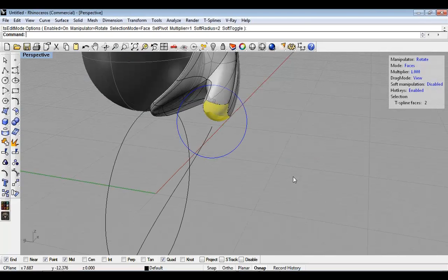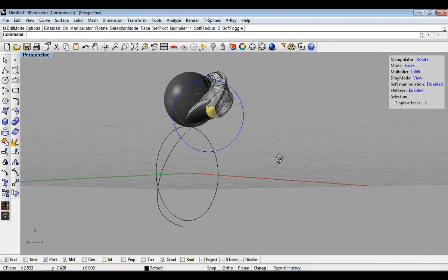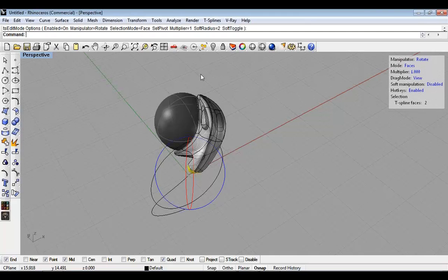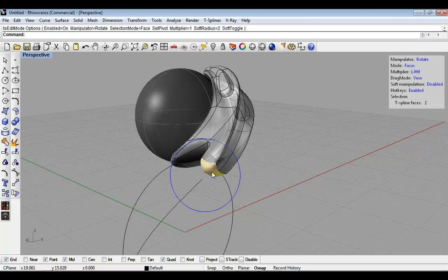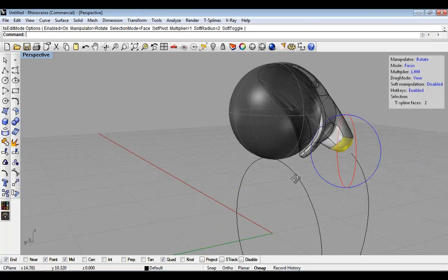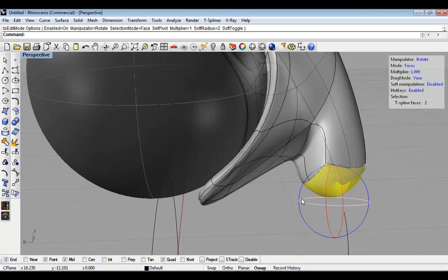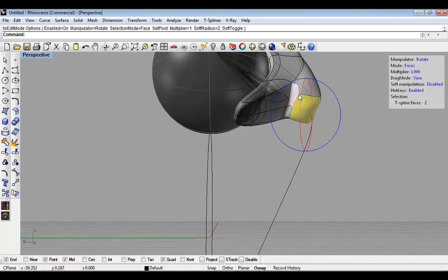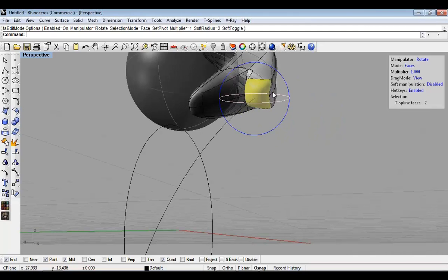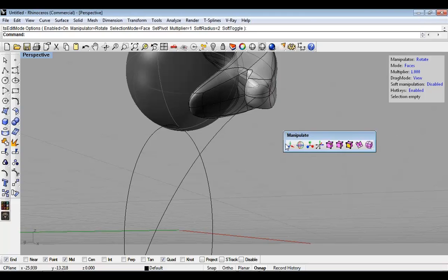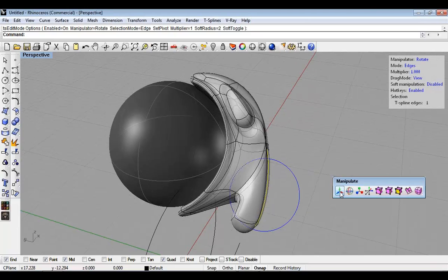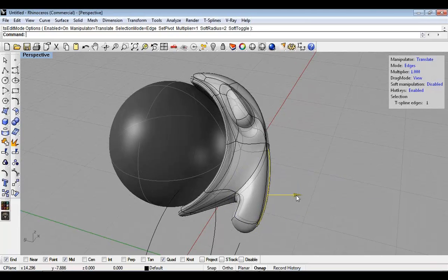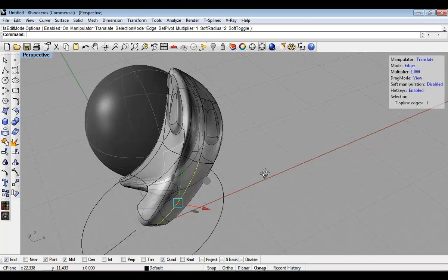And then the other thing I want to do before I start deleting faces off this is, while I need a hollow inside the snake's head up the top there, the snake's body in fact is round on the top and flat on the inside. So I pretty much got the flat part of this sorted on the inside already, but I don't need a hollow near the top. So I'm going to grab this edge over there and I'm going to pull it out a little bit. I'm going to get myself about there, and let's pull that out a bit. I want to get this looking kind of round.